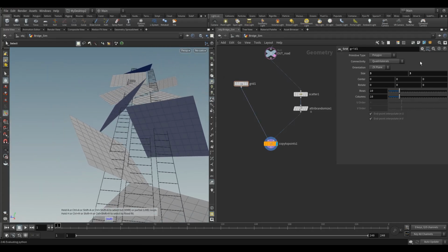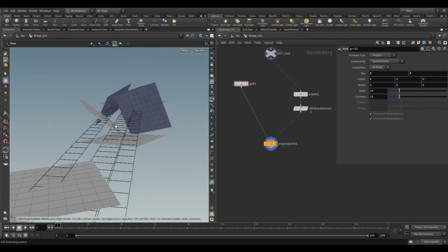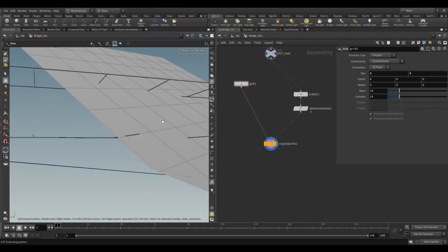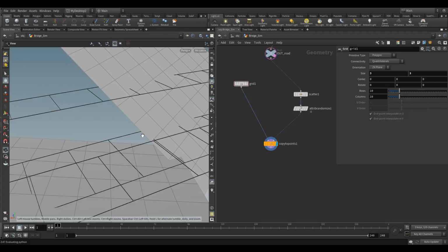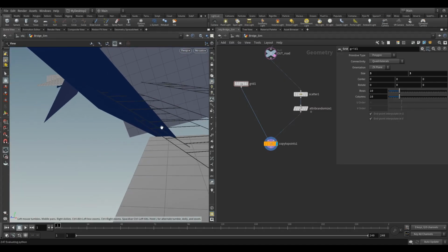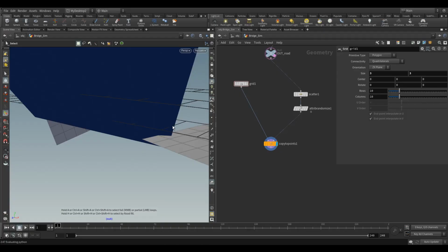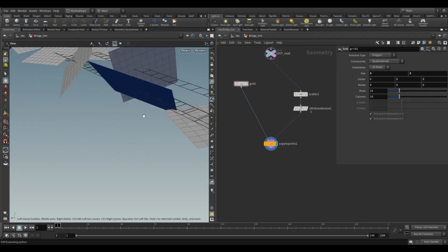Don't worry about copying the scale, we're going to change this again in a minute. So things like that, the cutting geometry only going part way through the geometry that you want to cut, that's no good. That's going to be problematic with our boolean. We want it to go all the way through in every direction.